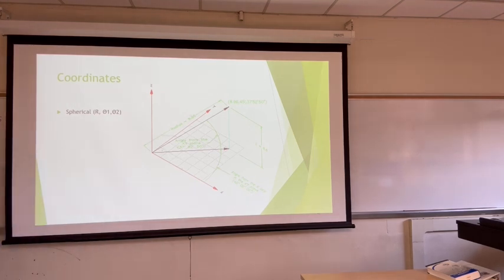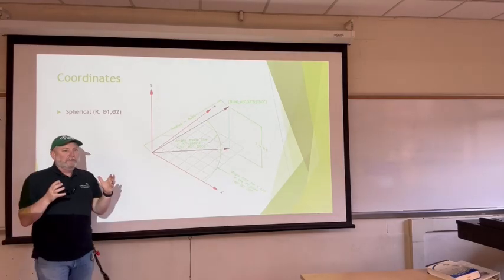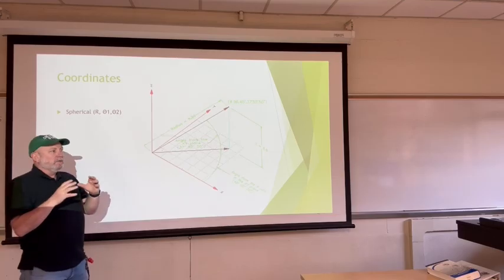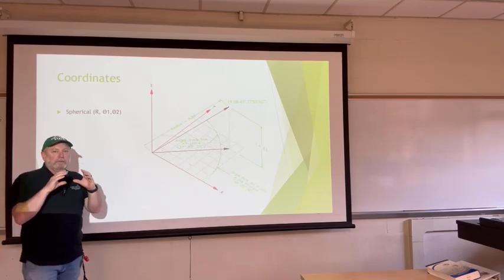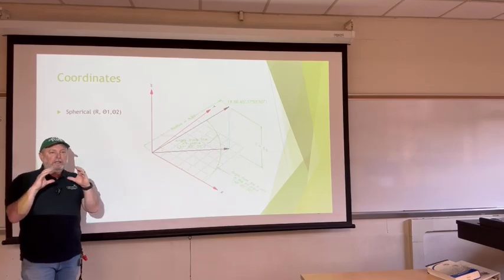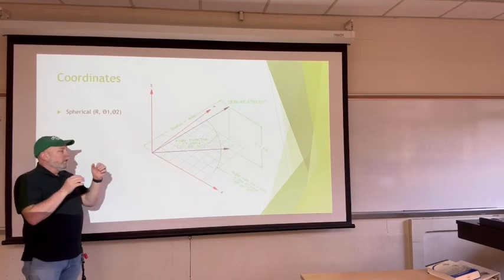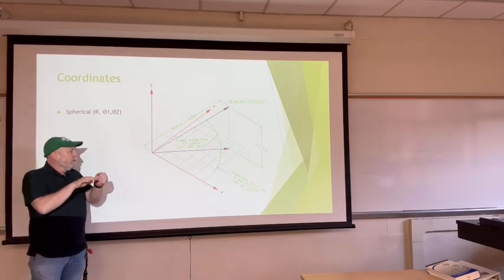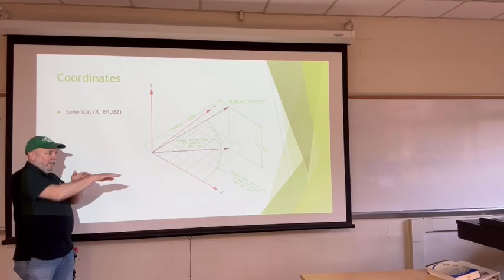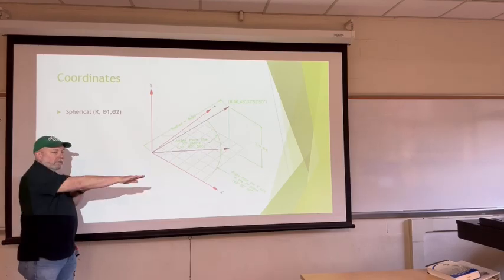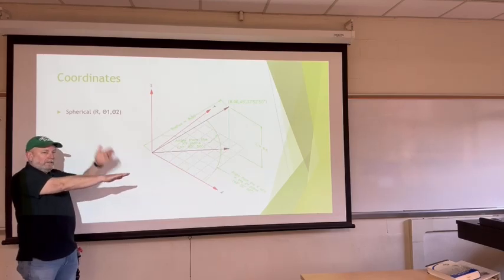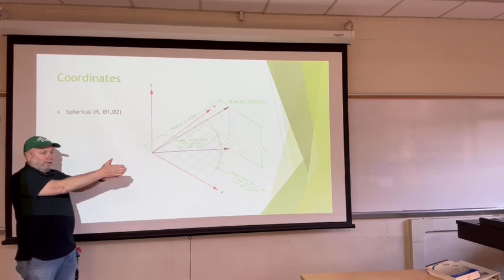Yeah, this is a little confusing, kind of hard to think of. I guess to think of it in surveyor speak, we talk about our geodetic datums. We have an ellipsoid, which is a smooth, perfect mathematical model of the shape of the Earth. The origin point being the center of mass of the Earth. Think of your x-axis as going from the center of mass out to the equator. So there's the Greenwich longitude meridian line. That's 0.